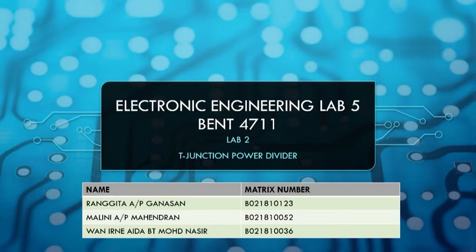Theoretically, a power divider is a 3-port microwave device that is used for power division or power combining. In an ideal power divider, the power entering into port 1 is equally split across the two output ports and vice versa for power combining. There are different types of power divider such as T-junction, resistive, Wilkinson and hybrid coupler.